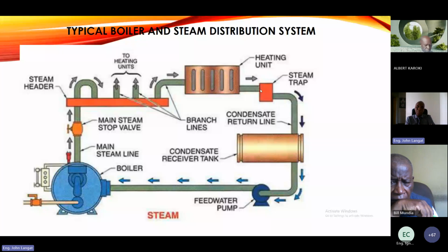So from the steam trap, it goes to a condensate receiver. After the condensate receiver, then we have a pump. I'll still share at the end the steam distribution system itself, now the condensate loop, and you'll see the setup for this condensate recovery system. This is normally a tank which supplies water to the pump. This is the feed water pump. You remember the two pumps I showed? This is the position it is on the steam system. Then it pumps back into the boiler.